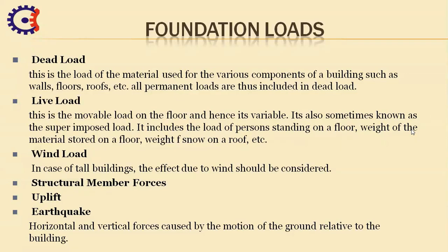Dead loads are in general the most important loads in foundation design, particularly for structures whose footing rests on soft cohesive soil. Dead loads, being permanent forces acting upon the structure, may cause considerable settlement, damage, or shear failures. Dead load is the weight of the structure and it is a permanent part. The weight of the foundation itself and the weight of the soil on the footing are also dead load. In estimating dead loads for the purpose of foundation design, the actual weight of the construction material must be used.